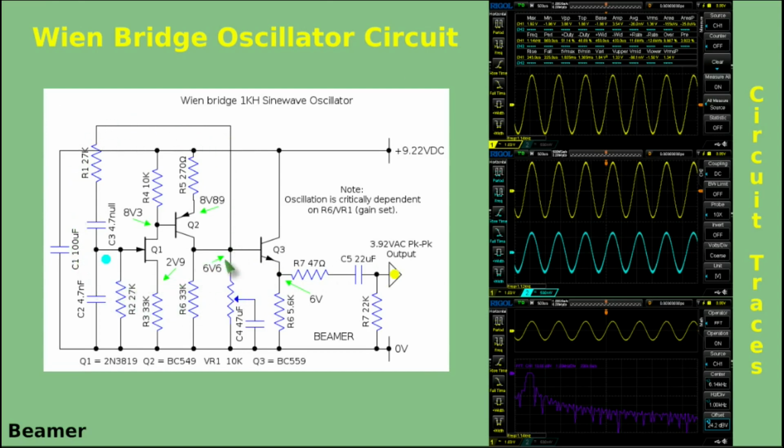Wien Bridge oscillator. Regarding the Wien Bridge itself, there's a peculiarity with Wien Bridge networks, and that is that whatever signal's coming in here, by the time it's arrived at its equilibrium point, zero phase shift, at this point here is almost exactly a third in terms of voltage peak to peak as there is on its input. And that is true no matter how you change these components here, the R's and the C's. They always have to be identical, the R's and the C's.